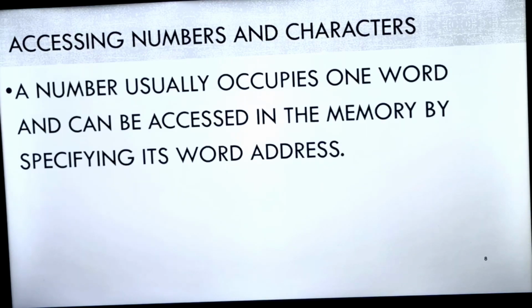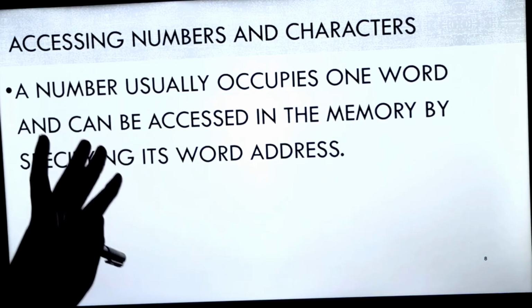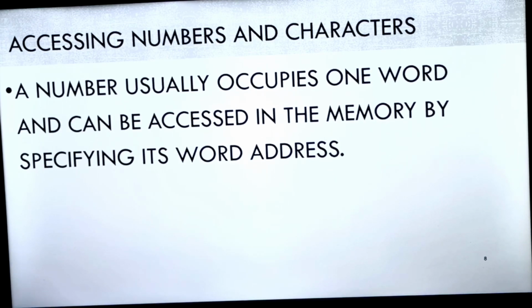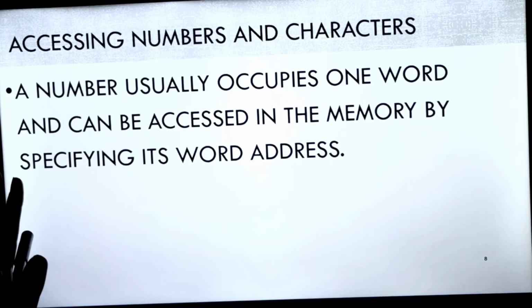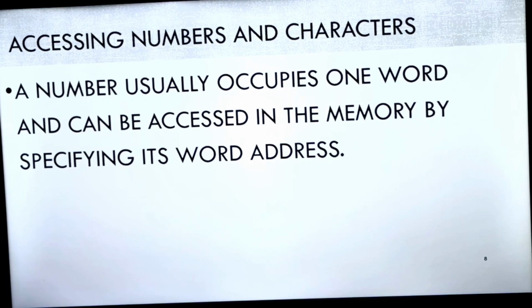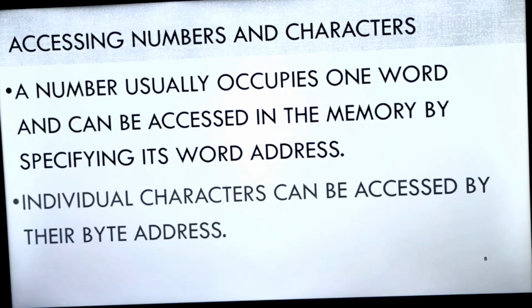So next is accessing numbers and characters. We know a number usually occupies one word. Why one word? I need 4 bytes to store a number. We know that I am talking about integer numbers. So 4 bytes is equivalent to one word. This is a standard or typical word length, 4 bytes. Fine. By default it's 4 bytes. And for characters, as I told you, one byte is necessary to store a character. Means one typical word can contain 4 different characters.